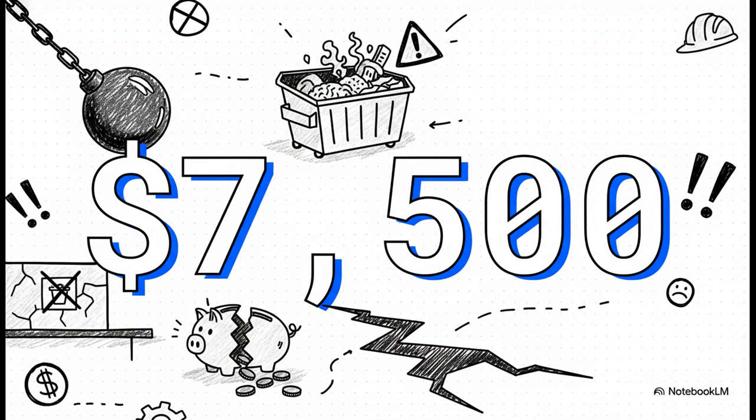So the crucial point is really this shocker of a number right here. If you try to cut corners on waste management, the penalties are just staggering. For example, unlawfully disposing of asbestos anywhere that isn't certified to accept it is an immediate violation. The massive minimum fine for this is over $7,500, or up to 5,000 penalty units if they fully prosecute the case. Proper waste estimation isn't just about being a good environmental steward. It is literally about protecting the entire project from catastrophic financial penalties.